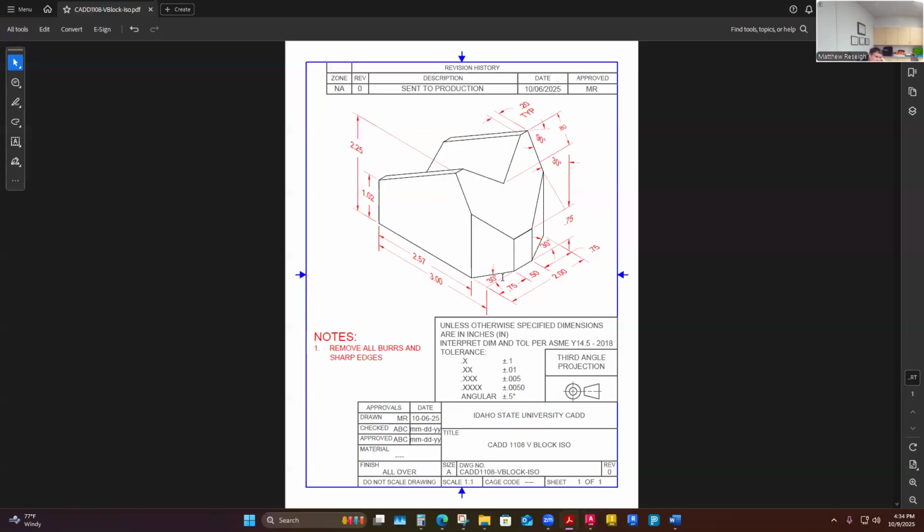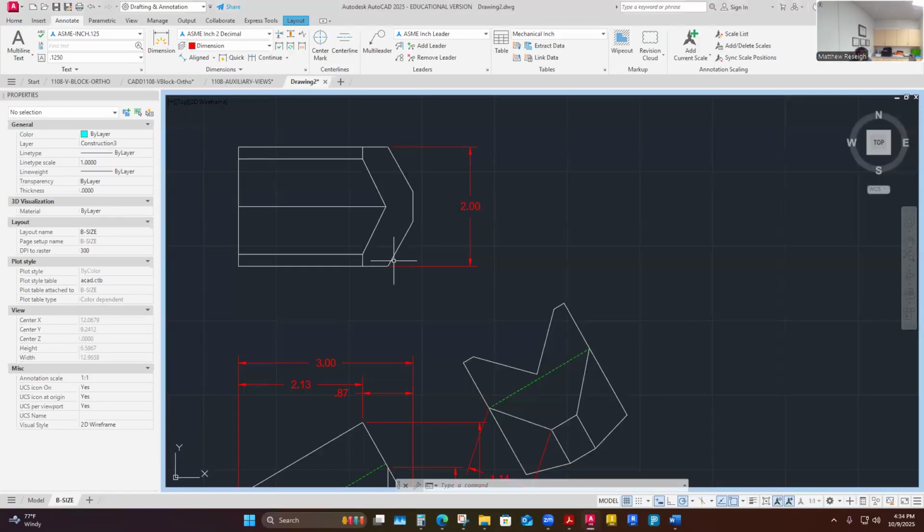Yeah, let me just take a look at my object right there. I'm looking straight down on this, and this surface is going to appear as an edge. This thing is not leaned back and coming towards me. It's straight up and down right here, from bottom to top. So I'm going to be able to see this true length right here in the top view. And that's all the sides of that trapezoid now. So to me, it becomes a top view dimension where it appears as a true length. So I jump back over here, and that's this right here.